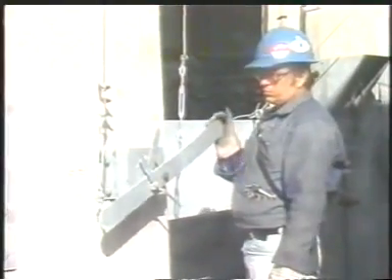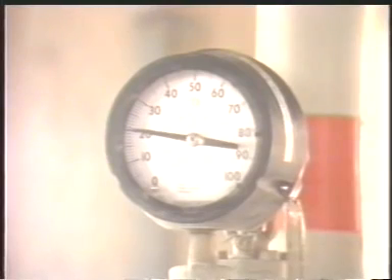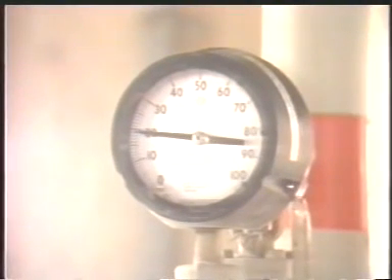As the burners are being lit, you adjust each air register for the proper amount of oxygen and the proper flame pattern. Then you adjust the damper for the proper draft. During the light-off procedure, it's also important to monitor the fuel pressure and keep it stable. Since the fuel flow is on manual at this time, there will be a tendency for the pressure to drop as you light additional burners.